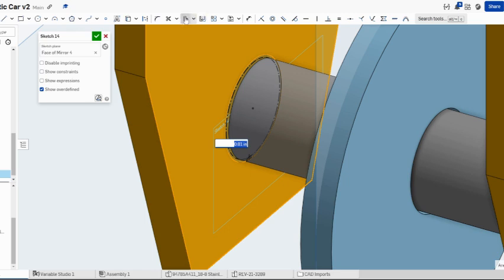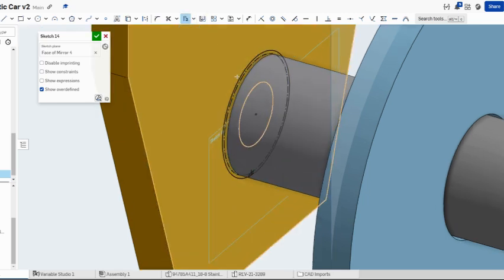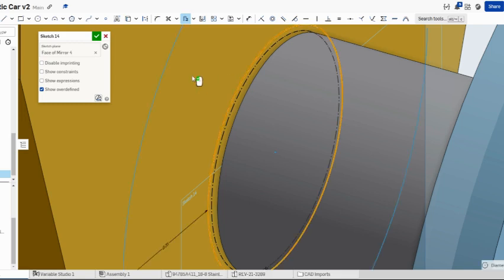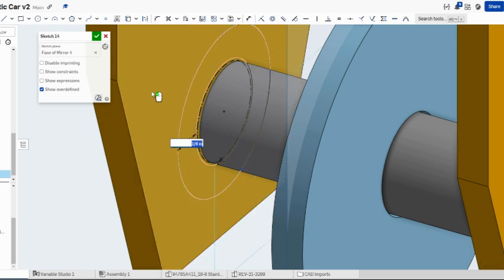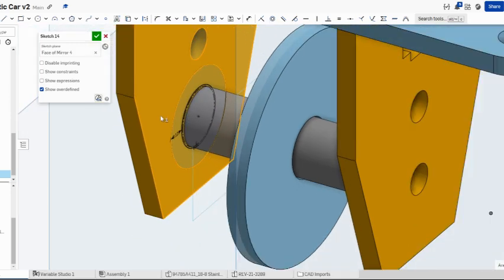I'm going to turn on the offset tool again. Now I'm going to click that black circle. And again, 1/4 of an inch is fairly large, so I'm going to change that. Double click, and I'm going to pick 1/8. So 1/8 space IN. If I've done 1/8 space IN, it will do the math. And 1 divided by 8 is 0.125. And if I click and hit enter, there is my circle.